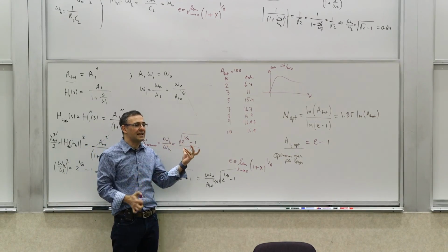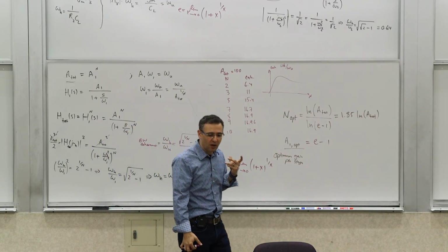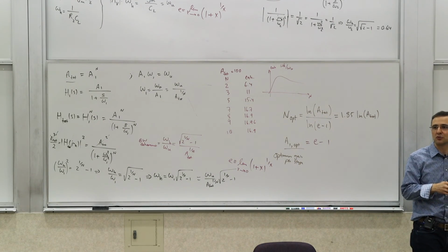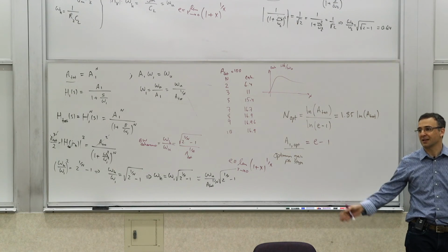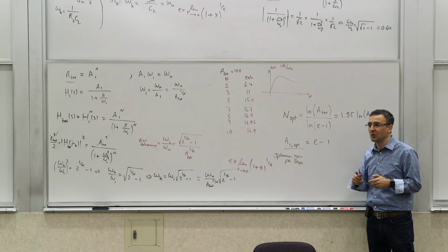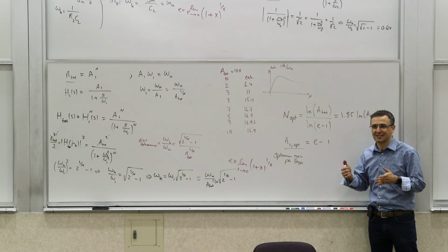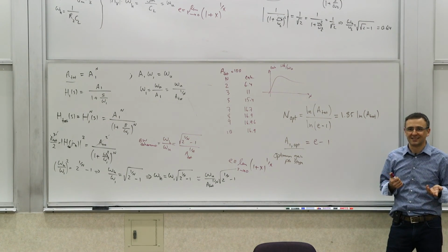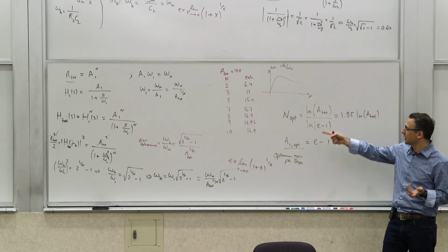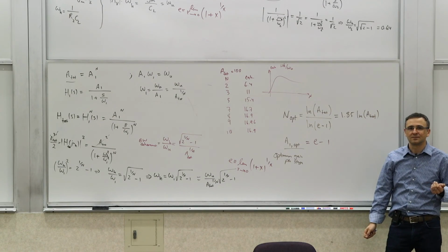So you can see that if you're designing wideband or broadband amplifiers, one of the things you can do is break your gain into a large number of stages as opposed to trying to get it all in one place. And you can see that the optimum gain per stage is pretty low, like 1.67 or something like that. It's not a lot. And it comes from this optimization. Any questions?